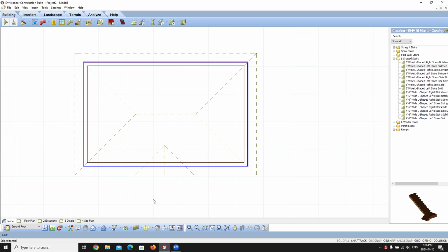You can also use the Roof by Picking Points tool to create a roof of a custom size and shape. This method is ideal for veranda or shed roofs. General editing tools like Move and Rotate apply to the entire roof itself. You can use the grips on a roof's corner and edges to resize and reshape the roof as needed. Each roof segment can be edited individually. By editing the properties of the different segments, you can create a roof with multiple pitches, plate heights, and styles.